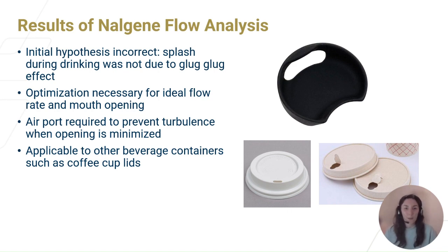So when we look at this black mouthpiece, it has two features that add value. First of which is on the bottom, that arc gives us an optimized orifice size to be ideal to drink from, both from a mouth perspective as well as a flow rate perspective. As soon as you add this orifice though, as we saw with the final video, you need some sort of hole in the top to allow an air inlet to allow for a steady flow. So we saw no matter how fast I tilted the water bottle with the mouthpiece in, it was effective due to this air inlet.